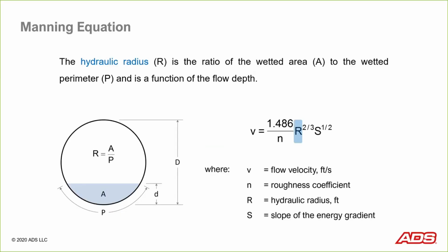So you figure out the geometry there and do that math, and you have something called the hydraulic radius. And once the pipe size and shape are established, and those are considered fixed, basically the hydraulic radius is simply a function of flow depth. And that's where depth enters this Manning equation.